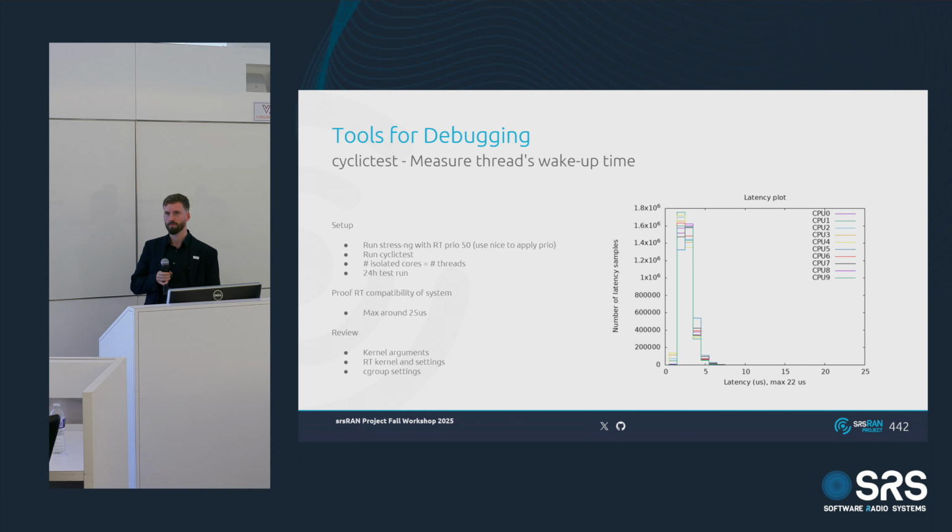How many UEs can be connected to this system? In general, there's no maximum UE, there's no hard limitation. We have tested with the measurement equipment that we have at hand up to 1,000 UEs in RRC connected mode. That is 1,000 UEs doing traffic at the same time, not idling, and this is supported on a single cell. So a little bit more than you typically have for private 5G networks.